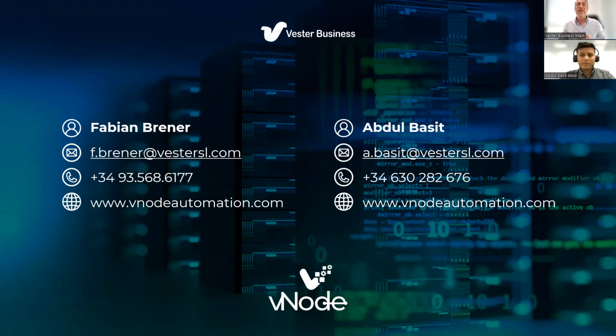How many devices, for example, in the software? We had projects where, in very powerful computers, we connected 800 PLCs, collecting Modbus data from all of them at the same time. So if you install vNode in a very powerful computer, you can make more connections, you can add more tags. If you install vNode in a very small, low power computer, you can move, I don't know, 5,000 tags, 10,000 tags, and of course, fewer connections. But there is no limit in the software. The limit is in the hardware you're using. Perfect.